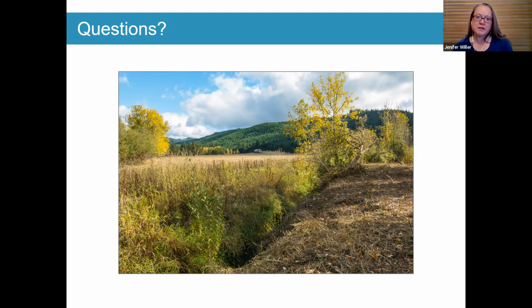The next question is, how much influence do the dimensions of the computational mesh have on model results? That's also a very good question. And luckily they're not super sensitive, but as you could see in the screenshot I had there of the computational mesh, we did make it a lot denser in the vicinity of the road crossing.